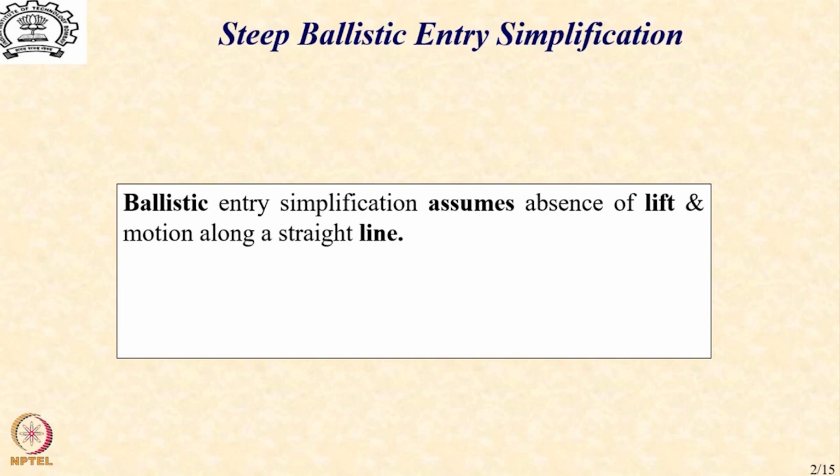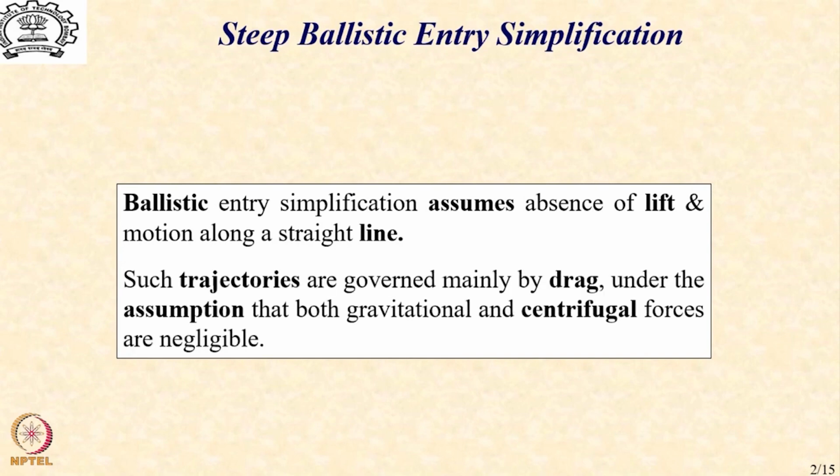As we have already seen, the ballistic entry assumes that there is no lift, and broadly the motion is along a straight line. As we immediately note, such trajectories are governed primarily by drag under the assumption that both gravitational and centrifugal forces are negligible.